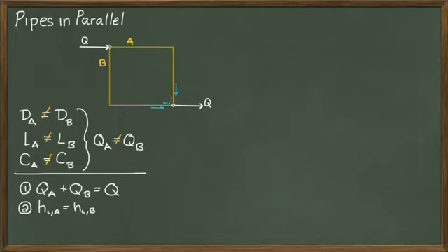Another way to think about that is if the head loss in pipes A and B were not equal, then the result would be 2 different pressures trying to abide in the same place when the fluid stream joins up again. That is not possible unless there is some barrier of some sort to prevent the 2 flow rates from interacting. Ultimately, there will be just one pressure head at the junction as the 2 flow rates join back together.